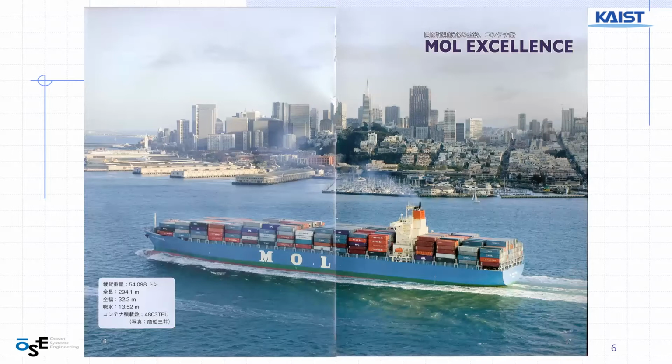Now we see the container ship, and it looks like the numbers at the left lower corner say that the deadweight is 54,000 tons. Overall length is about 294 meters, and breadth is 32.2 meters. And this breadth number, 32.2 meters, is very popular among many ships because this is the maximum breadth that can pass through the Panama Canal.